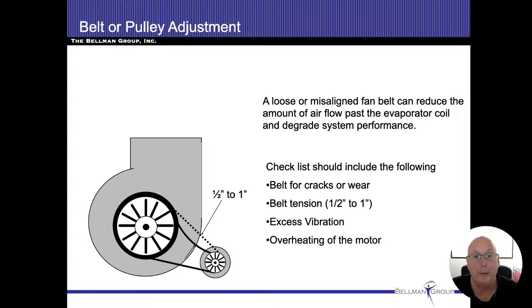you better be preparing your clients that they're going to be needing a new furnace or a new air handling unit. It may run forever, but I just kind of want to plant the seed and put the thought in their head. I would also encourage them to get an extra belt of the right size and have it just sit right down there on the floor inside that cabinet in case it's needed. Belts do break. It's just a matter of time.